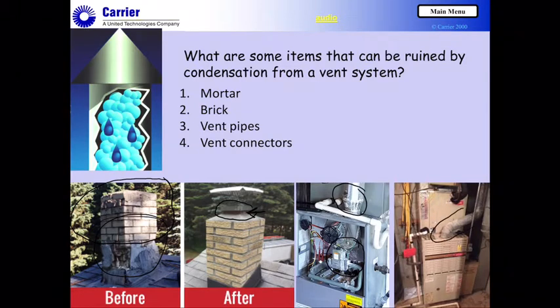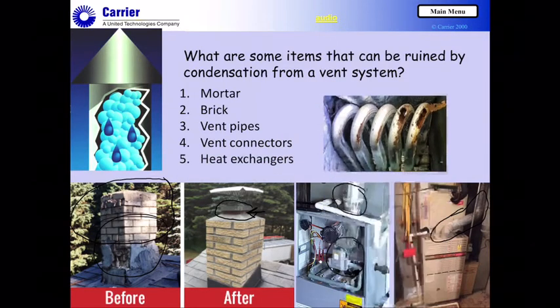On the picture on the far right here, you'll also see there's an excessive amount of condensation that's been occurring. The cover's not off in front of that furnace, but that's a little bit of a problem. The water runs back, it's acidic, it's going to be a problem.